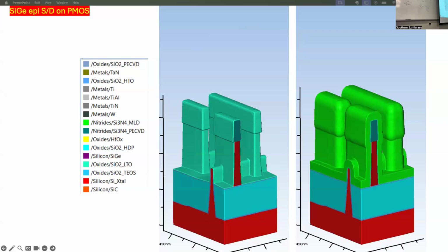Okay, so it's still going to be a 3D topology, right? Yeah. And so in that case, how would you do it? Because you're going to do an anisotropic etch, right? So say this is the fin, right? So what you're going to do is you're going to put a polysilicon like this, right? So it's going to be something like this. And then on top of this, you deposit oxide or nitride, and then you etch down, and then it's going to create a sidewall spacer like this.